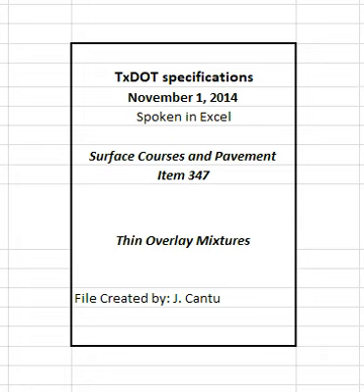Use the procedures described in Tex-233-F to plot the results of all quality control, QC, and quality assurance, QA, testing. Update the control charts as soon as test results for each sublot become available. Make the control charts readily accessible at the field laboratory. The engineer may suspend production for failure to update control charts.